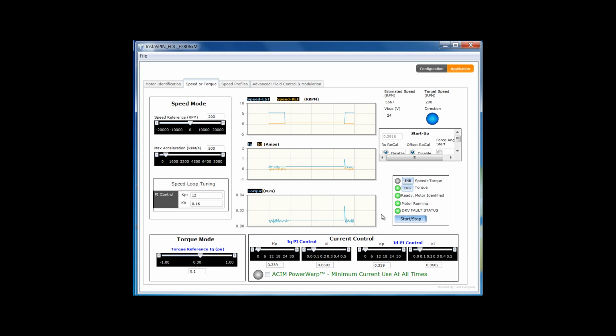But I'm also keeping that constant torque input. And now as I load the motor, you'll see it go down. Just the load I'm providing with my hand is not enough. There's not enough torque to fully meet that, so you can see I'm getting some oscillation. So let's stop the drive again. Let's reduce this.